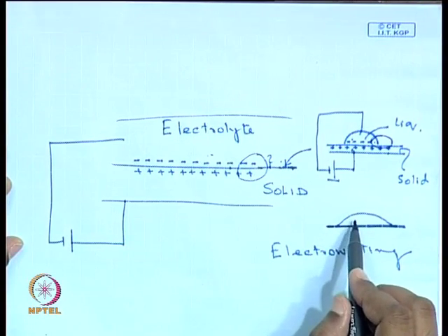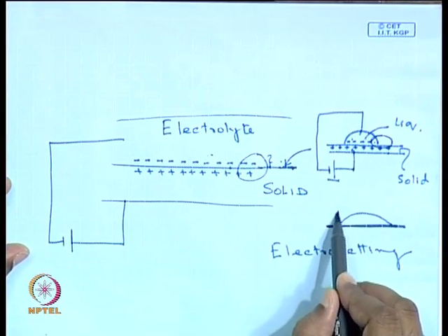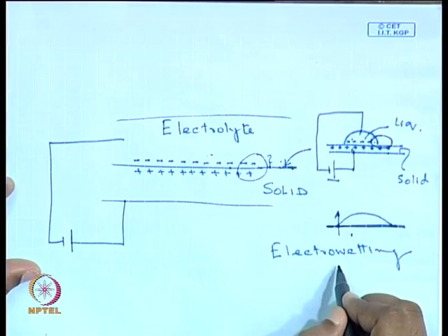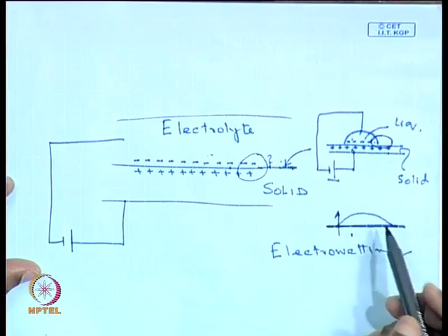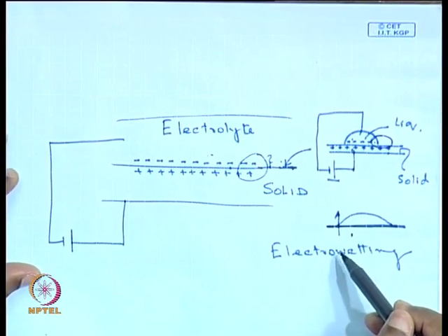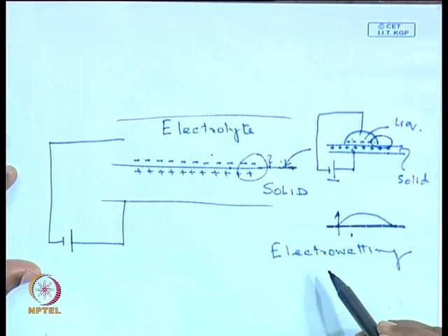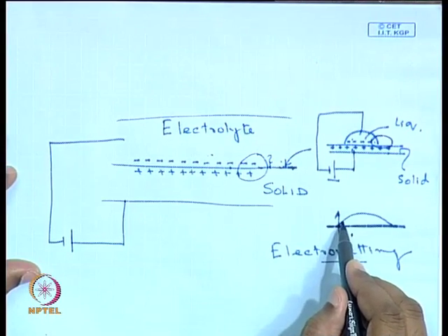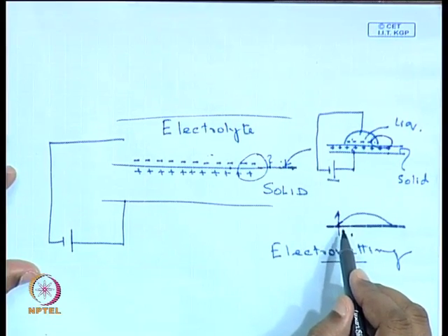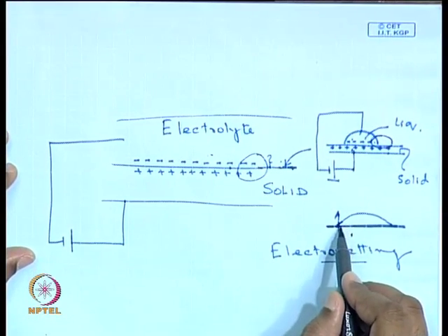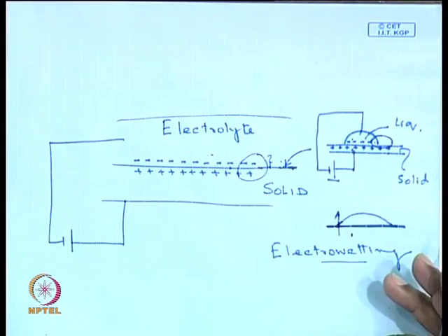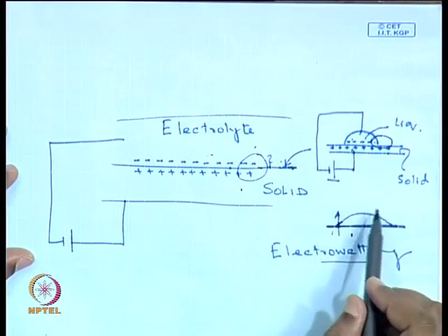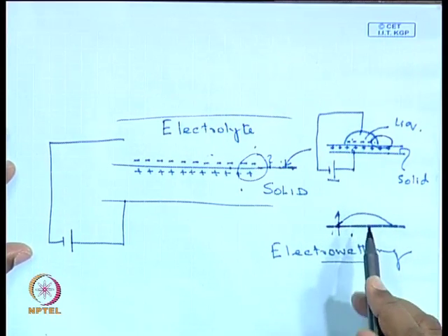If you would like to increase the voltage, then this process will break down, since a current would flow from the electrode to the electrolyte. So, only a few tenths of volts can be applied between the electrolyte and the electrode without passing a current between them. This severely limits the applicability of electrowetting in terms of appreciable changes in contact angle. We can only change the contact angle by a small amount, because any increase in voltage would lead to a current flowing between the solid and the electrolyte, thereby rendering the entire electrowetting process inoperable.